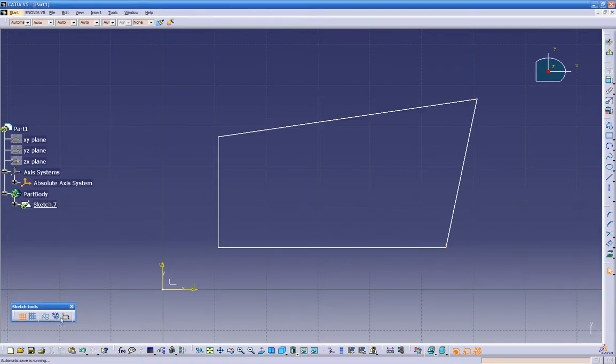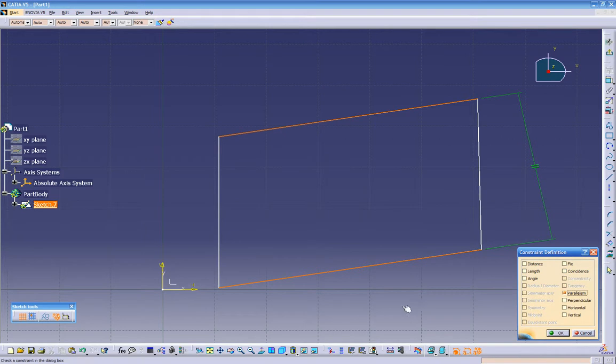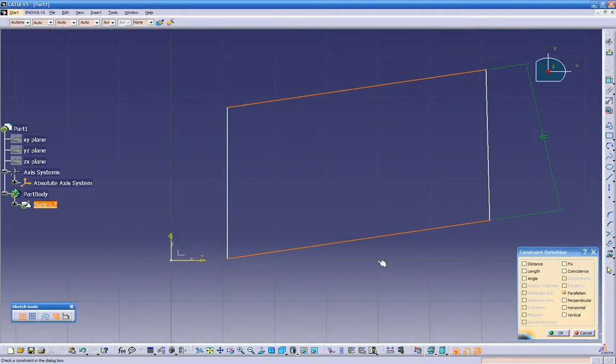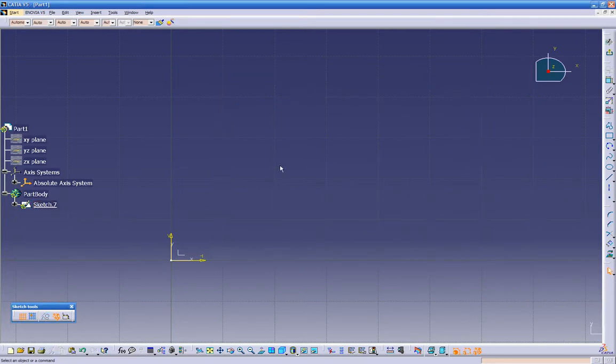And let's activate this option, the geometrical constraint. And let's try it again. Pre-select the line with this line. Let's go back to the constraint. And watch this, we're not going to get the alarm anymore. See, because we constrained it. So let's cancel this. Let's delete this rectangular, and let's try it again with this option already highlighted. And the same thing with the dimensional constraint.